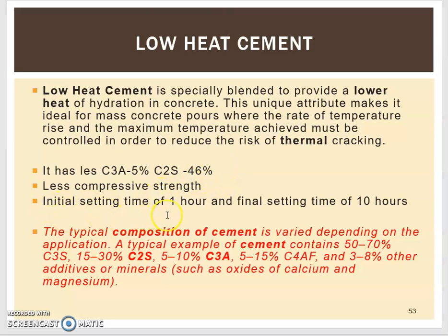It will usually exhibit lesser compressive strength as compared to Portland cement, and the initial setting time for this is around 1 hour, while the final setting time is around 10 hours.